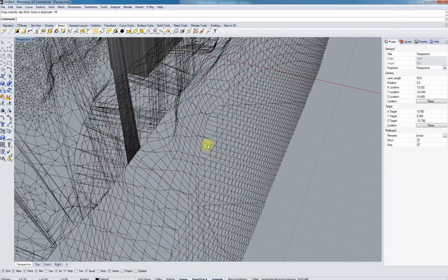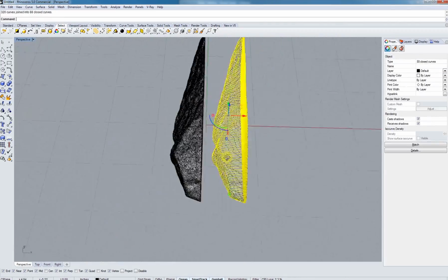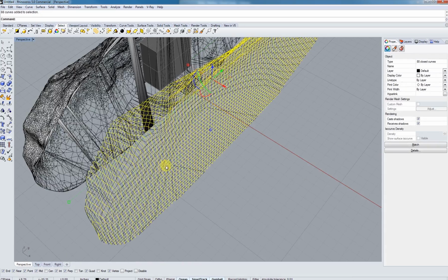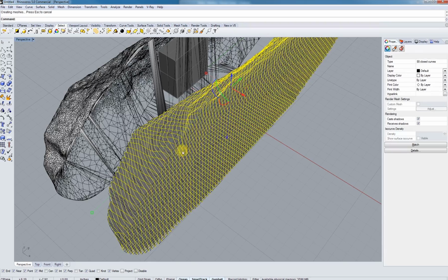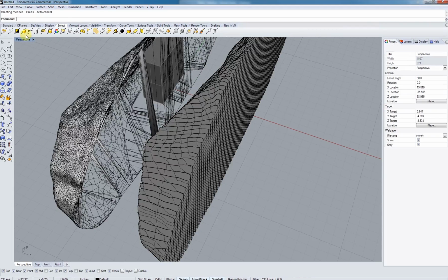And 1/2 inch again. You guys can vary your dimensions to whatever you like. I'm going to group these again. I'm going to join them. I'm going to move them over 10 inches once again. And the other set, I'm going to join them because I forgot that in the last step. Next, let's do our planar surface.